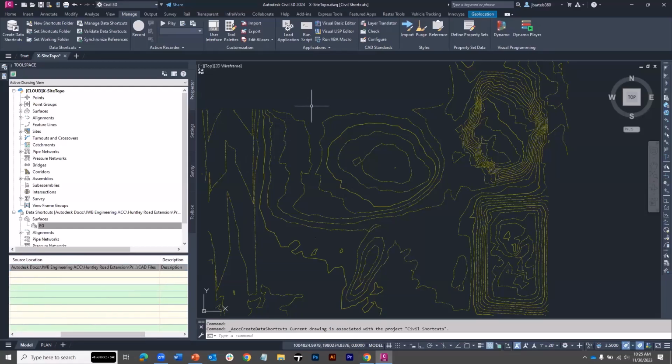All right, if you remember, when I create a template, I can create a template from an existing project. And an existing project, if it's a Civil 3D project, will have the data shortcuts folder with all those subfolders. If you create a template from an existing project, you will need to delete those folders. One more thing, if you create a template from an existing project, none of the files that are in that project go along for the ride. The only thing that you'll get are the directories, the role-based permissions, and any settings. So if you did have typical files you wanted to put in there, you would have to put those in there after the fact.